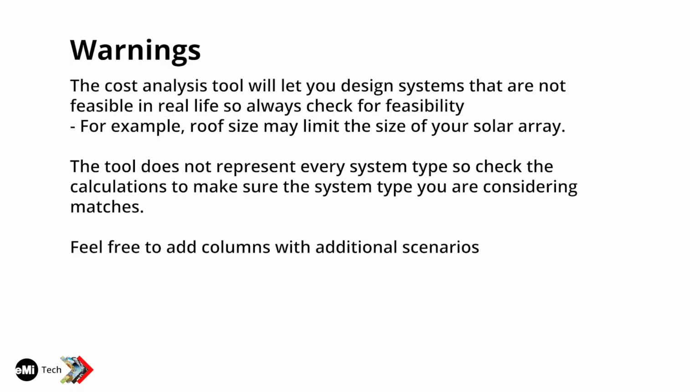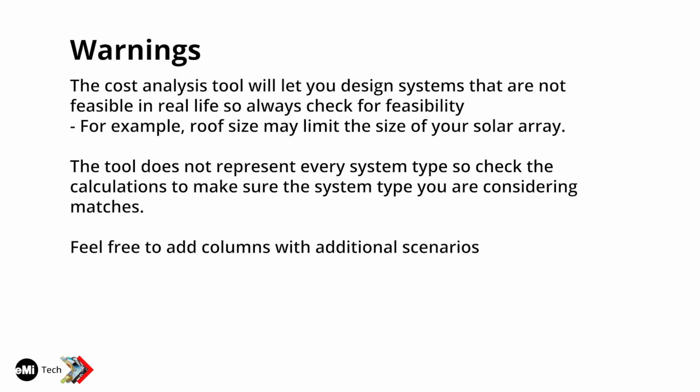You may have noticed that I said the minimum size for the battery system. So if it tells you to put in like one battery, that might not even make sense. Sometimes these integrated battery systems only come in certain sizes. So I went ahead and put a limiter in there to not allow you to put in a system that's lower than 180 kilowatt hours, because it's the smallest integrated system that we're aware of right now. But you're welcome to design any size system, but just keep in mind, I want to check and make sure this is feasible or just makes real world sense.